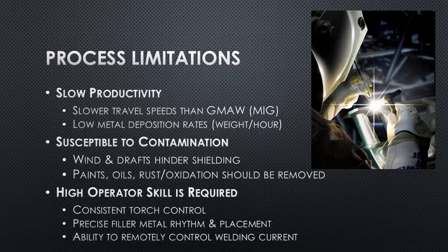Any paints, oils, rust, or oxidation should also be removed because it's going to contaminate your tungsten, it's going to contaminate your weld pool, and often result in some fume generation that's usually not very pleasant to breathe.